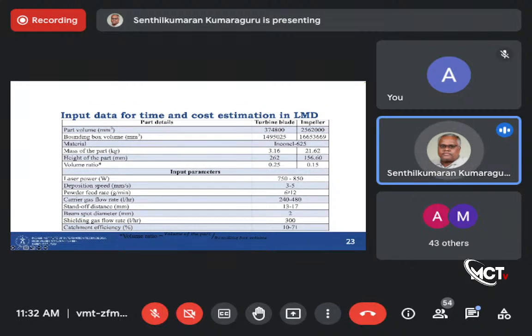And we use carrier gas to basically carry and shield. That is typically 240 to 480 liters per hour. And the nozzle usually stands at a distance. It increases the catchment efficiency. So there is a very important term called catchment efficiency. Catchment efficiency is like, at a particular instance, so much powder is flowing into the work zone. Only a fraction of that gets absorbed into the metal, and the rest can be reused, but still some of the powders that get into the melting zone actually melt on the fly.